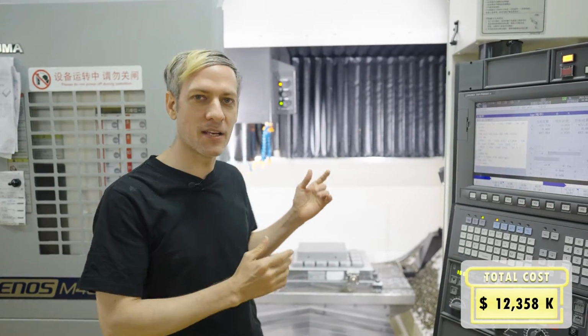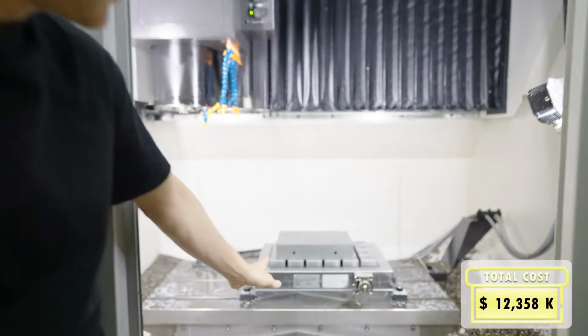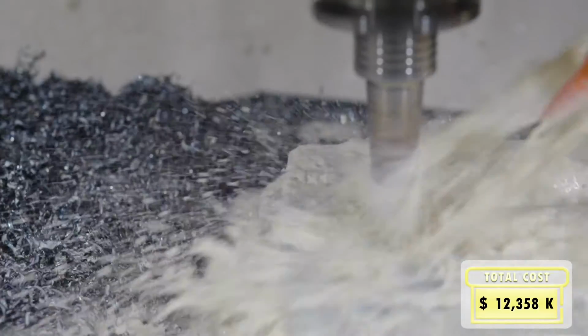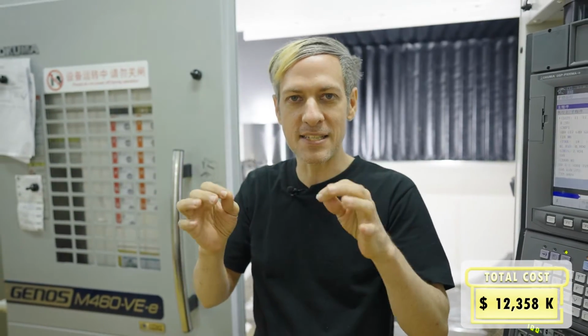So after the metal is ground square, they place it in the CNC machine, and then they're going to do a rough cut where they're going to cut the basic shape out, and they're going to cut this shape oversized so that later they're going to send the parts over to the more accurate machine, and then they're going to do the fine detailed work.